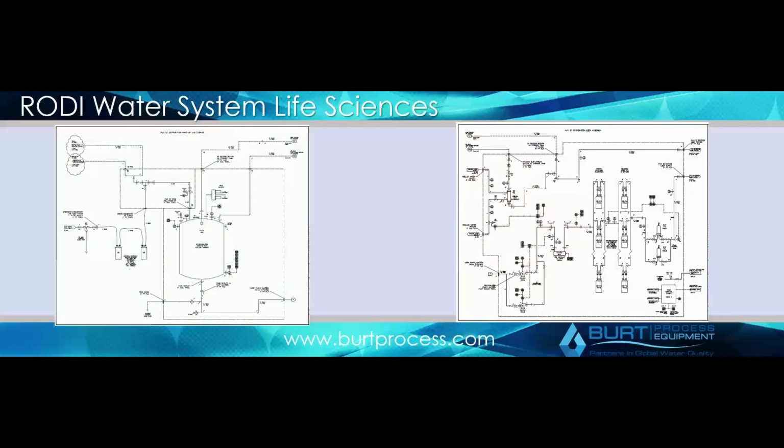And this is just one example here. Again, very similar. You have more of a sanitarily designed stainless steel storage tank here. This is actually off of a loop that already exists, and they're just doing some local polishing, in this case, sanitary tee-style filters. Again, in this case, sanitary design and bacteria really begin to become the primary focus of these different types of systems.